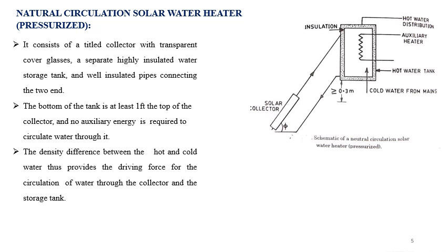As long as the sun shines, this water will quietly circulate, getting warmer and colder. After sunset, the thermosiphon system can reverse its flow direction, causing loss of heat to the environment during the night. To avoid reverse flow, the top of the absorber header is kept, as stated above, at 0.3 meter below the cold leg fitting on the storage tank. I hope you can make out.